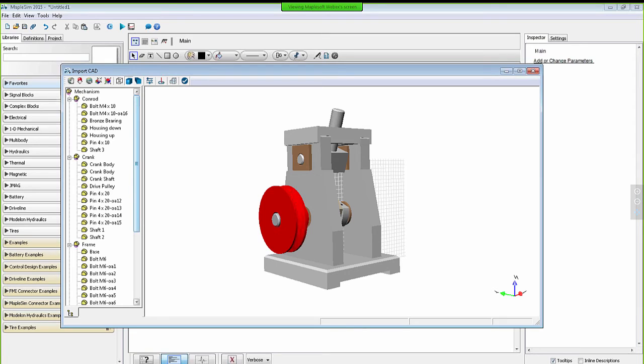So one other feature of the CAD Toolbox is that it gives you the ability to provide feature detection. And that's this button up here. The reason that's useful is rather than trying to figure out, oh, where's the center, what is the axis of rotation, I'm going to select here. You can see it can highlight the center of that circle, and it's added a coordinate now, and that coordinate's z-axis is along the rotation axis of that pulley. And you can see the coordinate I just added.